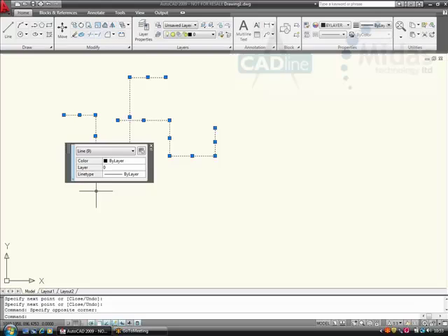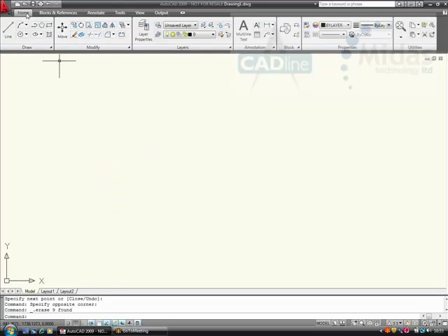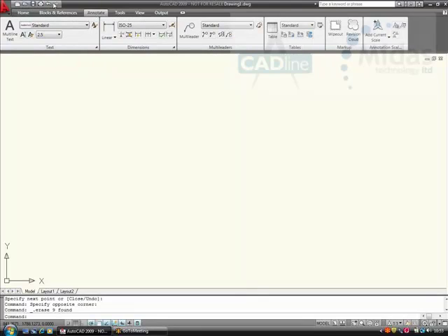One of the other features of the palettes at the top is we have this toolbar here called our Quick Launch toolbar. And this will give us all our favorite commands regardless what we're in here. So on mine, for example, I've set up New, Open, Save, Print, Undo, and Redo. So they're the ones that I would use all the time. So again, if I go to Annotate, that toolbar stays the same. This can be customized by simply right-clicking on it and choosing Customize Quick Access Toolbar. And in there you can add and remove the icons of your choice. The same with these toolbars here. We can right-click and customize, and you can customize them in what order you like.